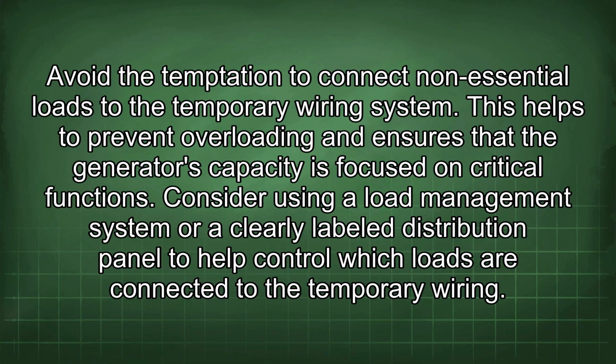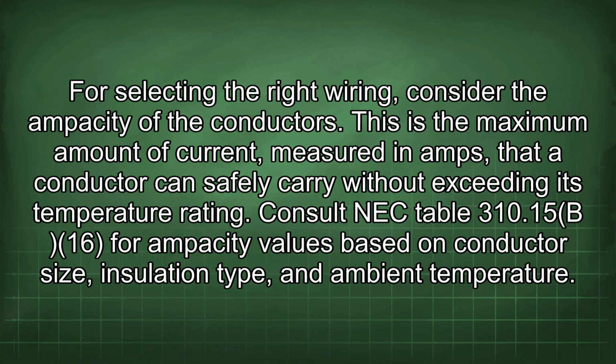This helps to prevent overloading and ensures that the generator's capacity is focused on critical functions. Consider using a load management system or a clearly labeled distribution panel to help control which loads are connected to the temporary wiring.